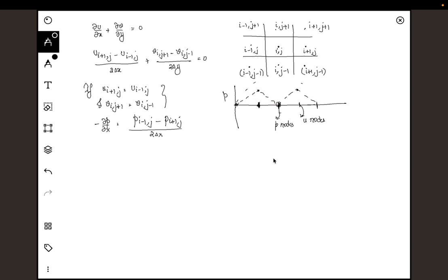Say, for example, velocity also follows a similar pattern, increasing, decreasing, like this. If you have a velocity profile like this, and I am not using the same grid but a different grid here, then in order to calculate the velocity gradient I would be using velocities at different points. Because I'm trying to update the velocity here, which is not 0, even though the pressure gradient is 0, it will see a different value of gradient over there. So your continuity equation will not be 0.